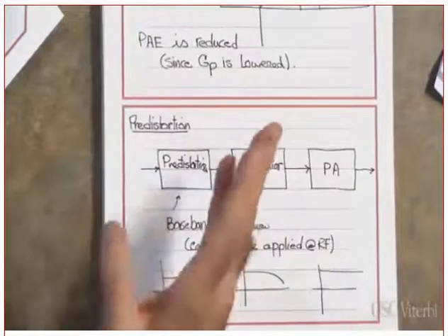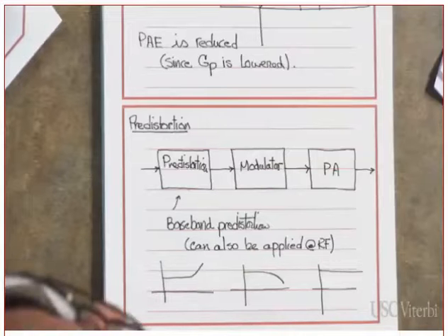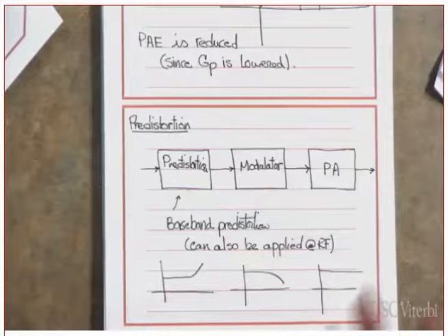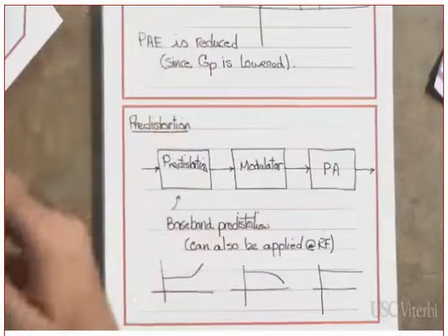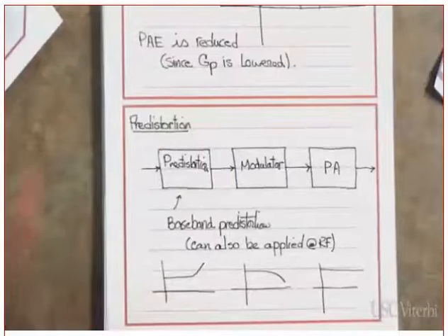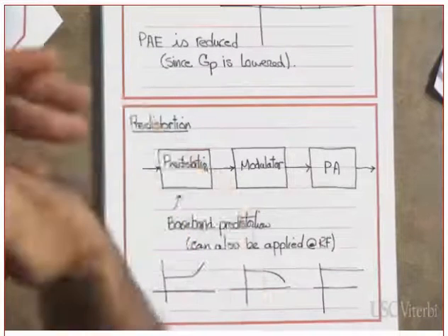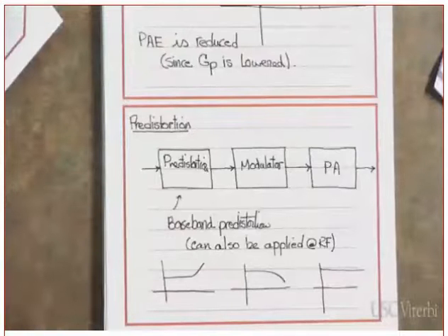This is called pre-distortion. Pre-distortion is also used in communications over wireless channels. You will take this in 535 when you use what is known as equalization. You are trying to model the channel characteristic, and you try to equalize it. Equalize it means when it's showing some dips, you need to show some gain, so that when you group them together, they will end up with a flat response. Clear? But we don't talk about equalization in this course.